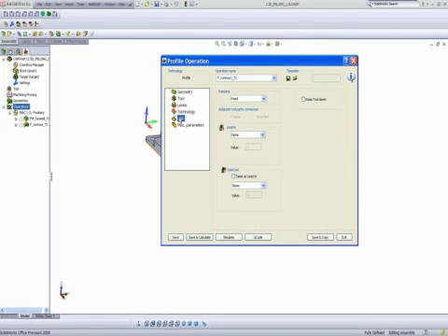Now, my link, in my lead-in, I'll again choose the option of arc. Now I have excess material on this side, so I'll leave this at, let's say, 5mm for the lead-in of the arc. In other words, 5mm from here to here. And my lead-out, I'll use the same as my lead-in. I'll simply choose now save and calculate.